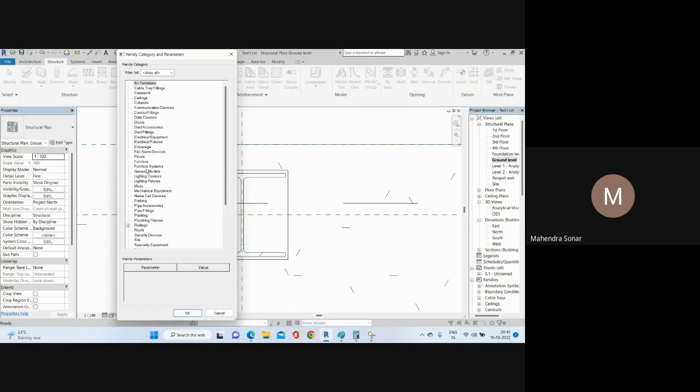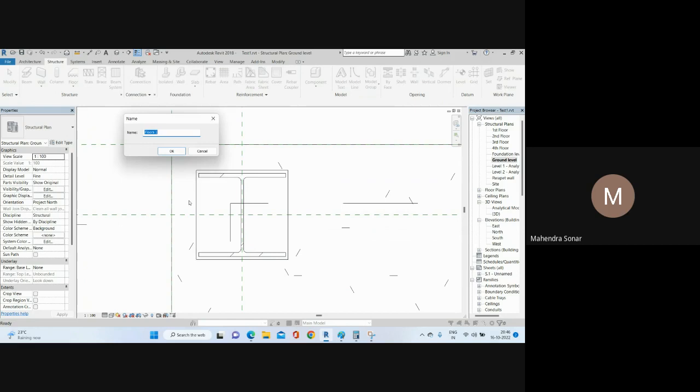All the grout is cement material, right? So you need to select this floor category. Okay, so always all the grout is resting on the floor slab here. So I will select this floor category and click here OK, and you can see here 30 mm grout and click here OK.